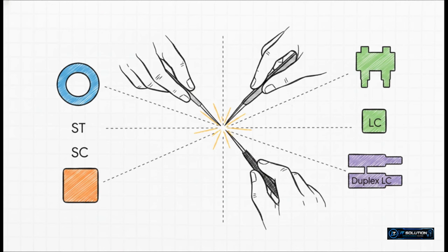But, of course, that kind of high-end performance comes with a catch. Fiber optics require way more skill to install and strict safety protocols. The engineering is just incredibly precise. You've got specific connectors like ST, SC, LC, and duplex multimode LC, all designed to make sure those delicate little light pulses align perfectly from one device to the next.